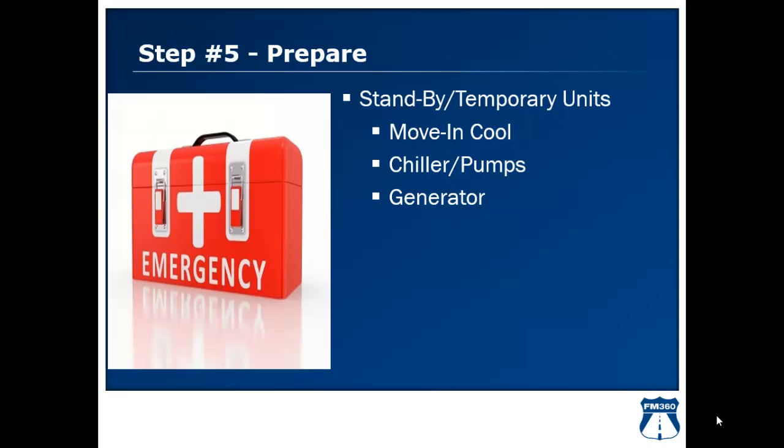What about a generator? If you had to bring in a temporary generator, how do you connect it? Do you have quick connects? Do you backfeed it through your load bank connection? Those are the type of questions you need to answer now and have procedures written around those.